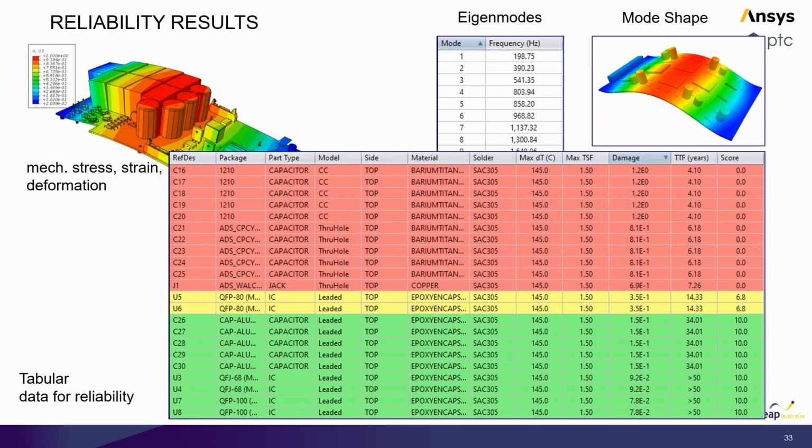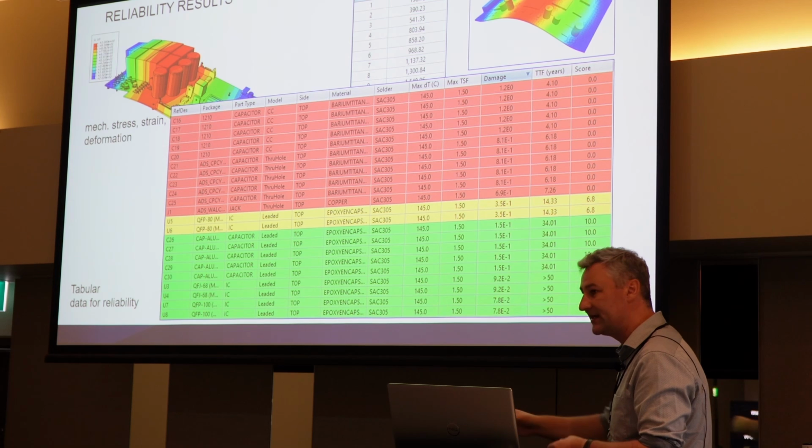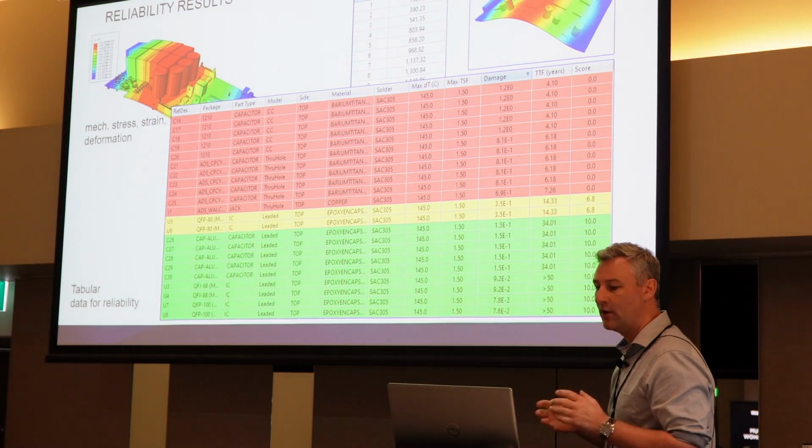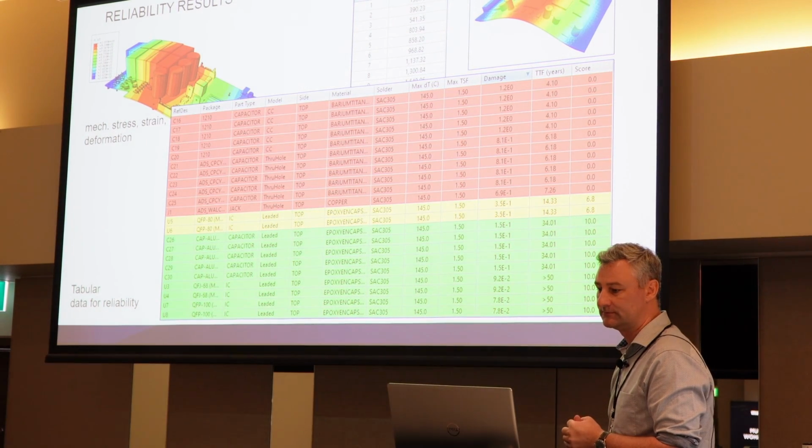And that's a couple of results. I think the life curve is just the most important and the star of that. But you also have the ability to drill down to your components. You can see this capacitor will fail after 3 years, or this inductor will fail after 5 years. So you have that, and the scoring system also shows you, is it a sudden death because the PCB has been dropped at a certain event, or is it a fatigue problem?